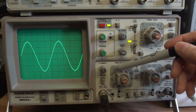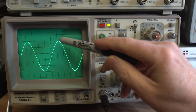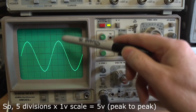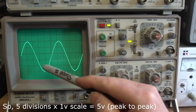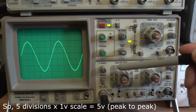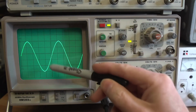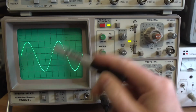You can see that this is set to 1 for each one. That's 5 high from peak to trough, so it's just 1 times 5. So this sine wave is actually a 5 volt peak to peak signal. That's not RMS or anything, that's peak to peak, just determined by the attenuator control. So straight away it's working like an AC voltmeter. We can see the voltage amplitude very clearly in the actual peak amplitude.